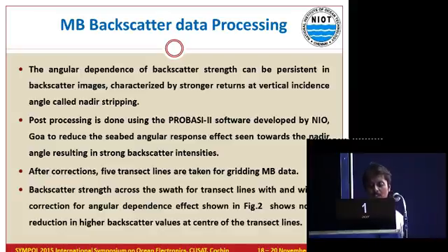Module 1 is for removing corrections like slope correction, heading and position correction and all. Module 2 reduces the angular effect in a coarser manner, and module 3 does the same thing in a finer manner. Module 4 applies low pass and high pass filters to remove the noisy backscatter signal.